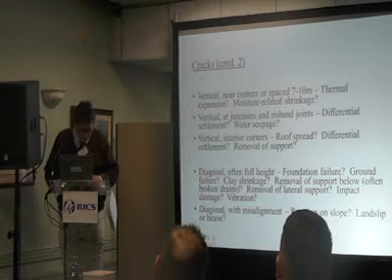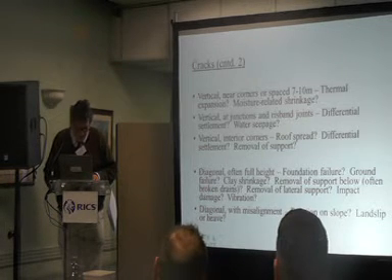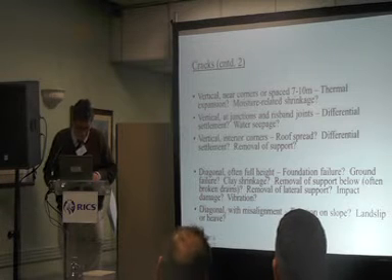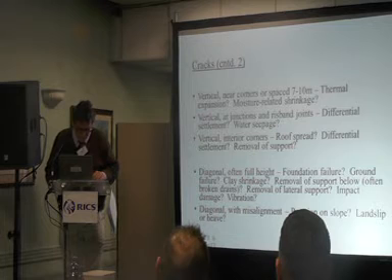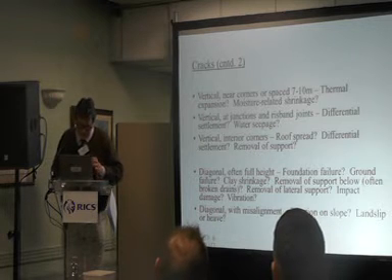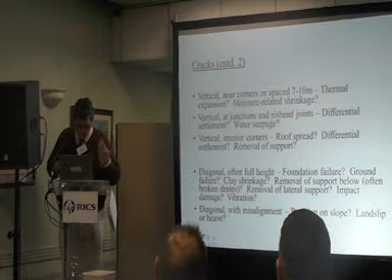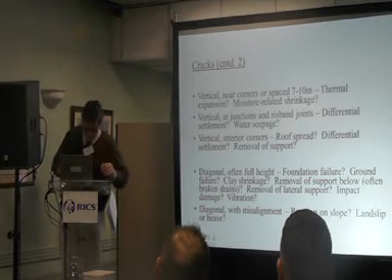Diagonal cracks, really these are our favourites, I think. They're often full height, and you get some corkers when you've got foundation failure, ground failure, clay shrinkage. Again, removal of support and broken drains. Sometimes removal of lateral support. If we've had a row of buildings, a terrace of buildings, and something's removed, there's no longer any lateral support, you get a diagonal crack.